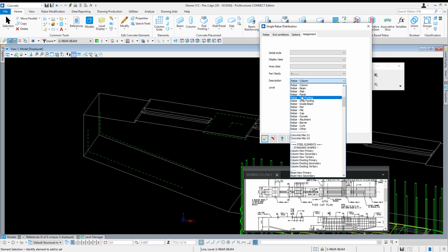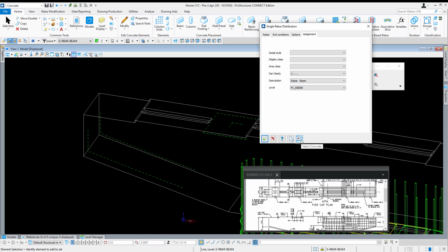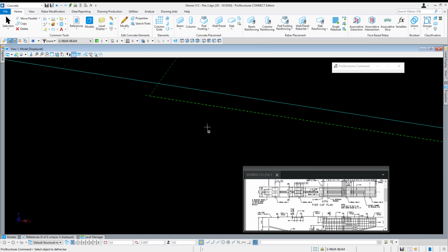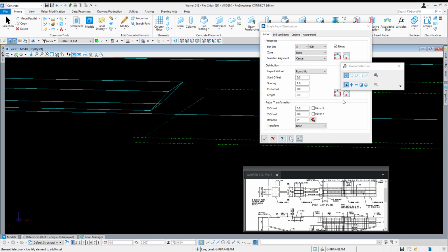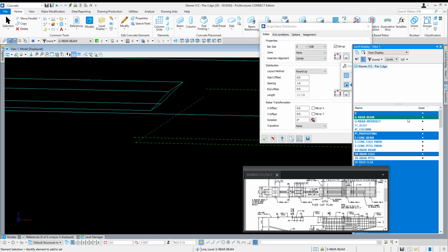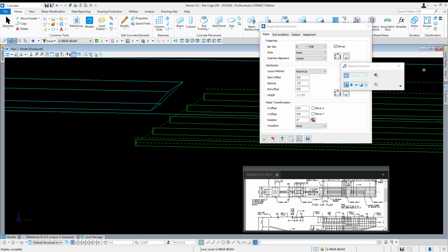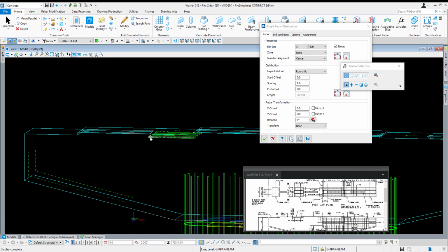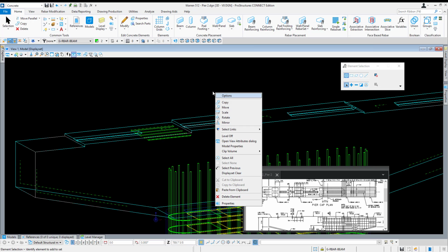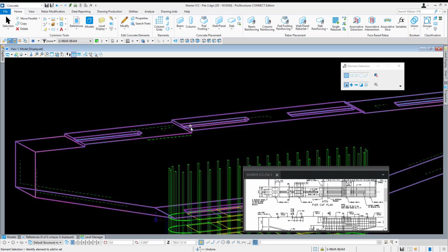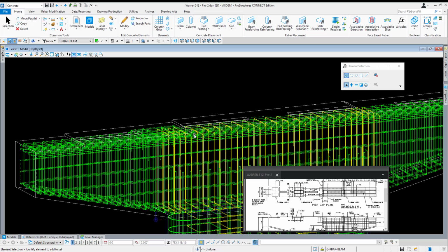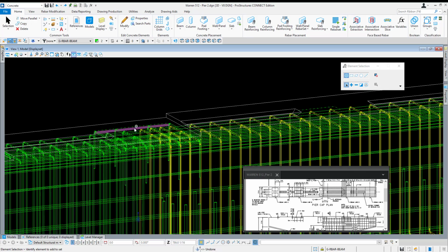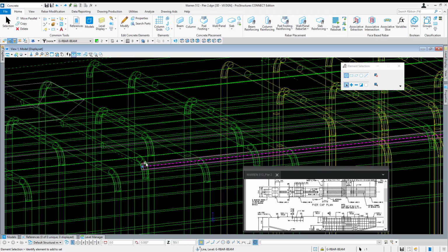On our assignment tab, SR, let's have our beam selected. Concrete, bar guideline, followed by path. Check our beam level here, looking good. And clear our display set. There we go. We have all of our bars now modeled, so I'm going to select all of the guidelines